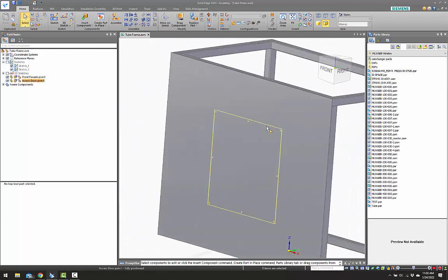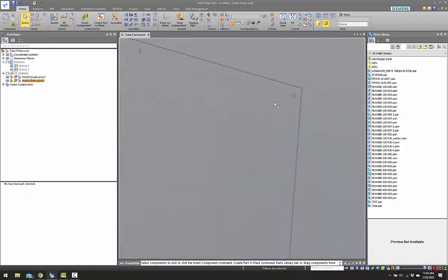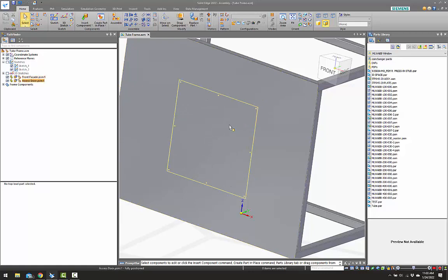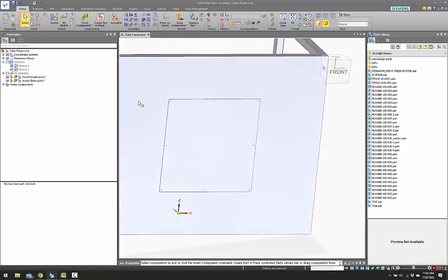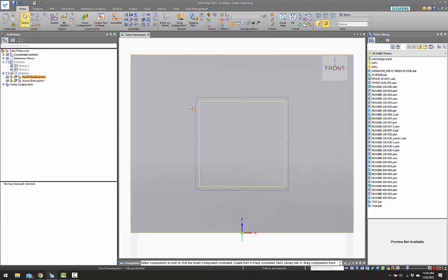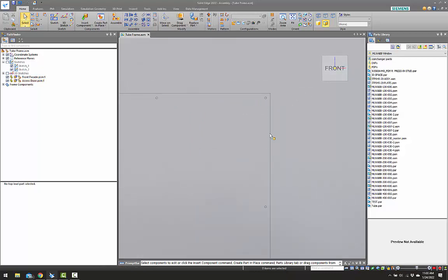And of course, we'll probably use some self-tapping, so we'd have through holes here and let them screw into that, which may be difficult. We may not want to use self-tapping. Yeah, we'll have to though. Better make that mild steel instead of 304. We'll never drill into it. But anyways, so there we have that.